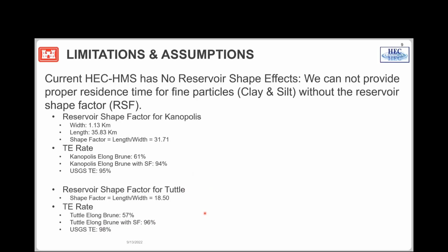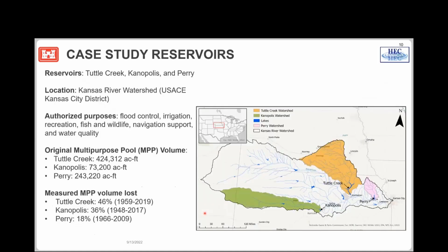With this limited situation, Nathan changed things in terms of calibration. We generated a gradation curve with 4 grain sizes, but we have limitations for the clay and silt. For calibration purposes, he changed some of the fine particle amount, silt and clay, to sand amount. Then we can properly calculate this case study better than without changing the gradation curve. We can manage the gradation curve manually, but if we implement this feature, then maybe we don't need to change the measured gradation curve that much. So I think that's my last slide. I'm going to turn it over to Nathan.